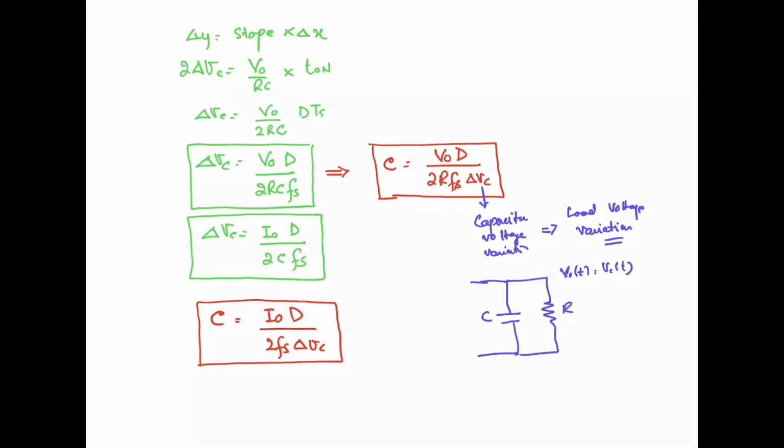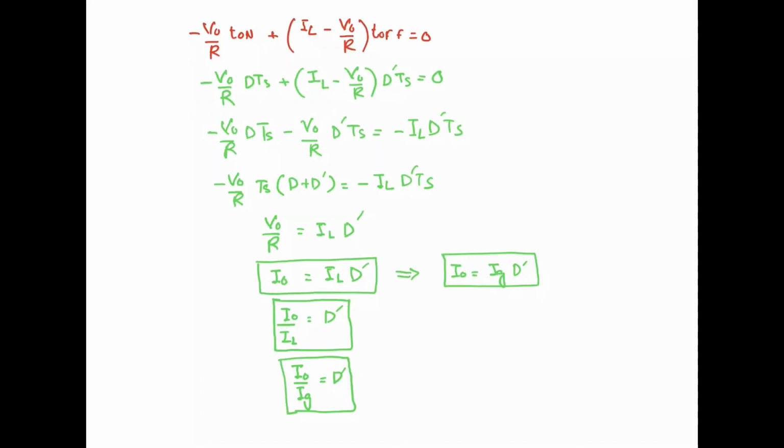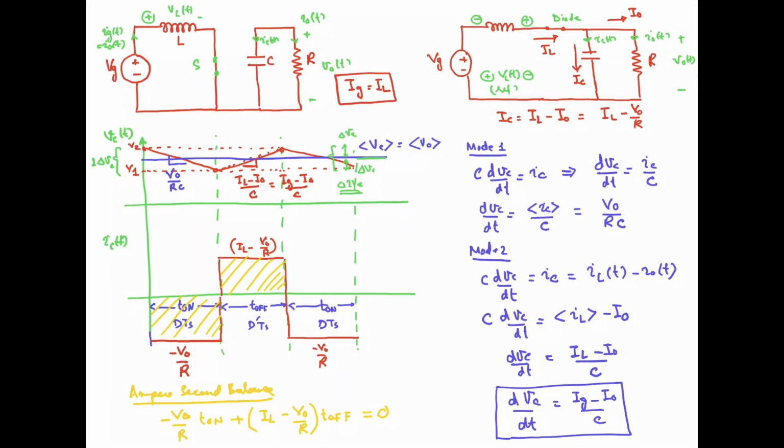And if I go back and look at this capacitor voltage waveform, if you decrease the capacitor, the variation in the capacitor voltage will increase. At one particular instant, for a certain duty cycle, or based upon load condition or capacitor value, you can reach the 0 point over here, right?